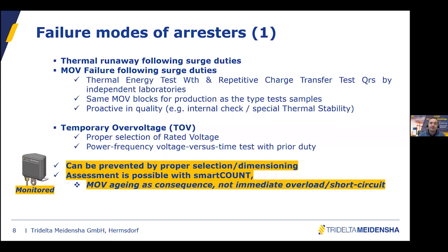You cannot predict everything. And the main cause of MOV aging is actually the surge duties and the stress coming from the system, which could lead to an evolution of the resistive current. So in that way, the smartCOUNT can help you to assess and look at the MOV aging as a consequence.